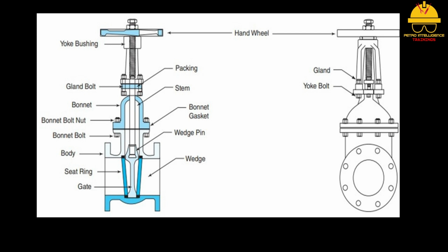The stuffing box is a recessed area specially designed to allow packing to be mounted around the stem. The packing gland is a device used to compress and secure the packing material into the stuffing box. The packing gland nuts are designed to be evenly tightened by a technician to stop leaks.